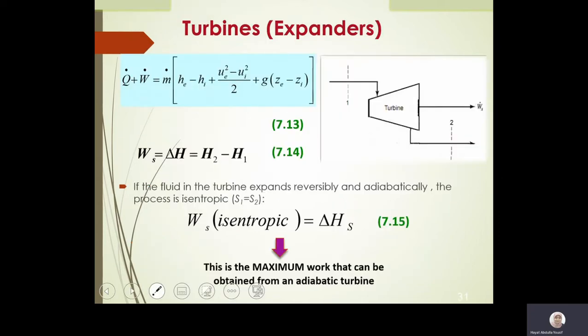All of you know the first law of thermodynamics. I already explained it for the turbine, and we cancelled the kinetic energy terms, we cancelled the heat transfer considering adiabatic, then no change in potential energy, then we will have the power equal to m dot delta H, provided of course that I have one inlet, one outlet. And this is the general type of turbine.